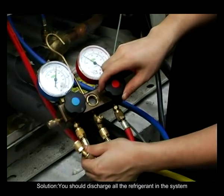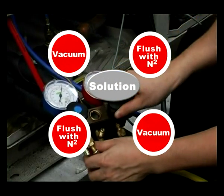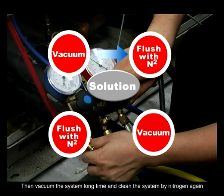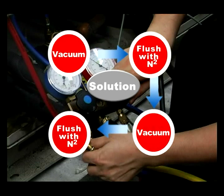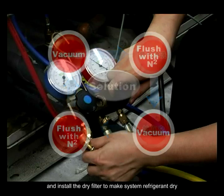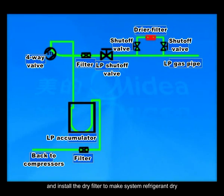Solution. You should discharge all the refrigerant in the system. Vacuum the system a long time at first and clean the system with nitrogen. Then vacuum the system a long time and clean the system with nitrogen again. Repeat the above process several times. You can change all the refrigerant oil if necessary and install the dry filter to make the system refrigerant dry.